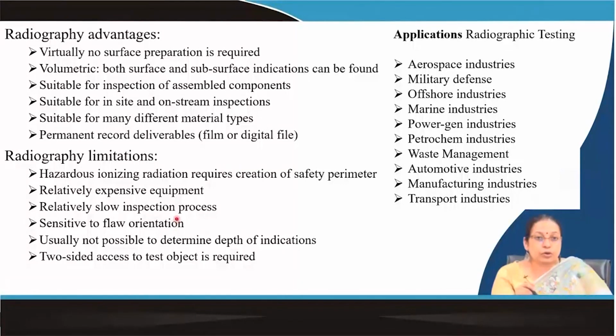It is sensitive to flaw orientation, it is not possible to determine the depth of indications, and two-sided access to the test objects is required. That is always good, and it has applications in aerospace, marine, offshore, power generation, petrochemical, waste management, automotive manufacturing or transport industries, anywhere as you wish.